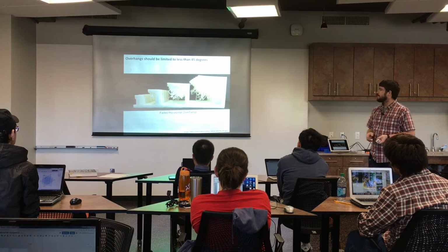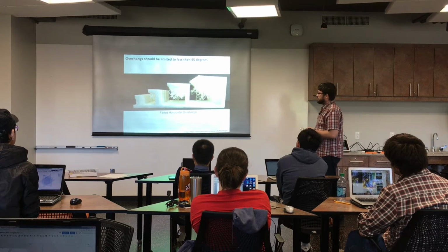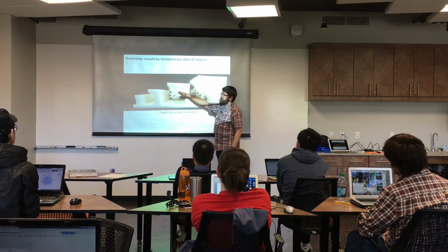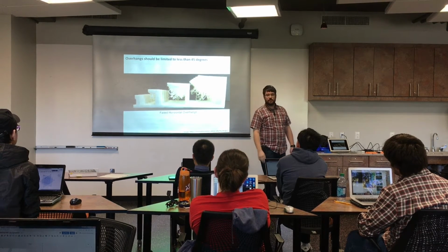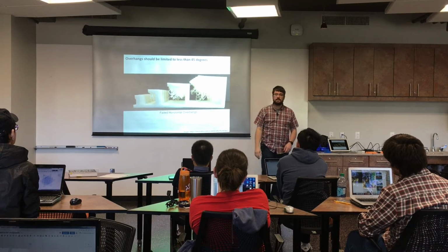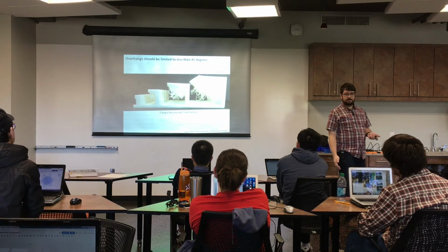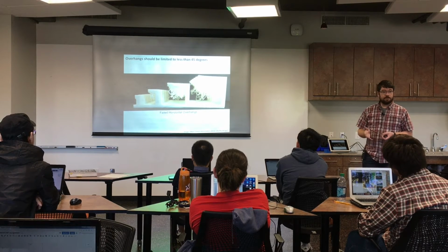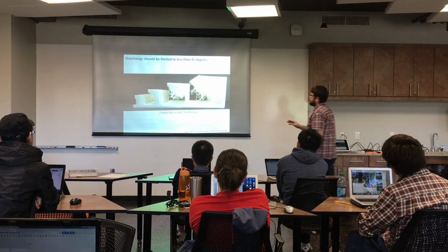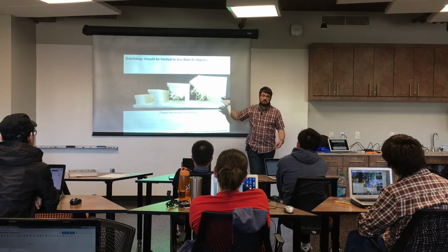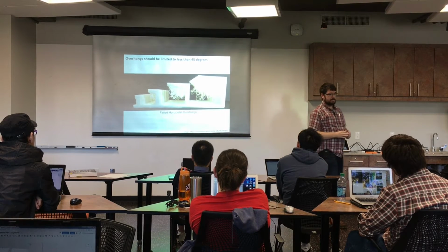Overhangs are another problem. And I actually have a part in the office that has this issue of if you try to go very far at an angle that's greater than 45 degrees from vertical, again, you start running into the printing in thin air and it just doesn't work. So you need to support that again somehow. You can have your tool generate support material for you, or you can manually go in and, for example, on this part, if it wasn't critical that this space was open, I would just add a tapered gusset there at, I don't know, 30 degrees from vertical or something, and then you'd be fine.